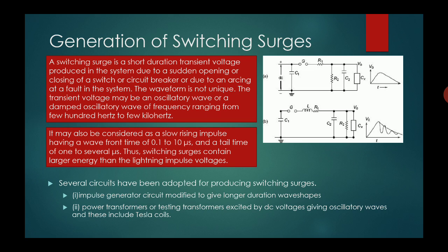The switching surge is nothing but a slow rising impulse having a wavefront time of 0.1 to 10 microseconds and a tail time of about several microseconds. Such switching surges contain larger energy than a lightning impulse voltage.